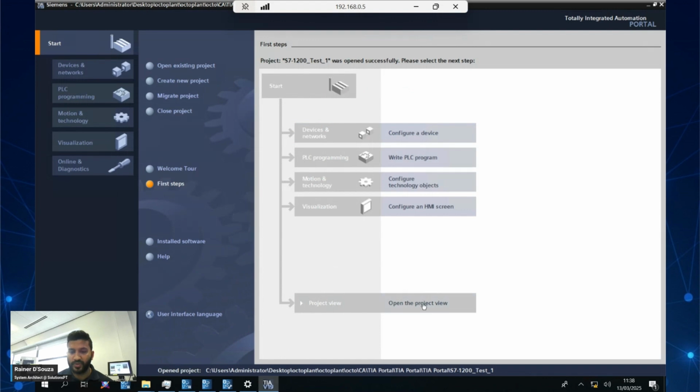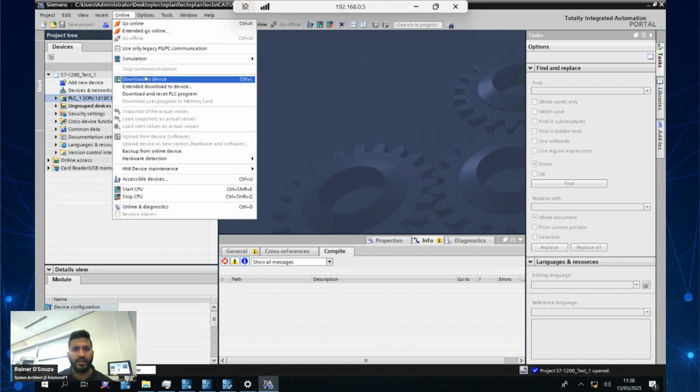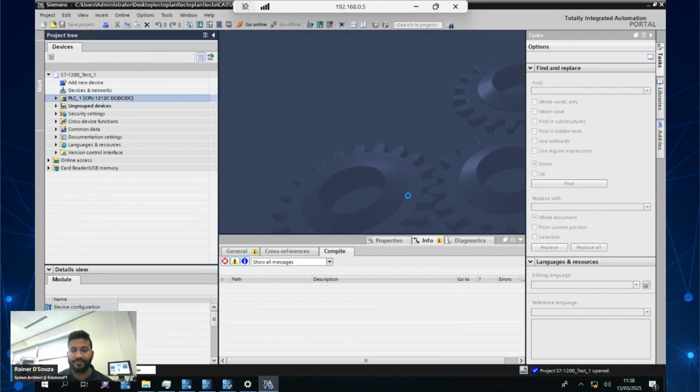So with my TIA Portal, I go to project view. I click on PLC, then download.